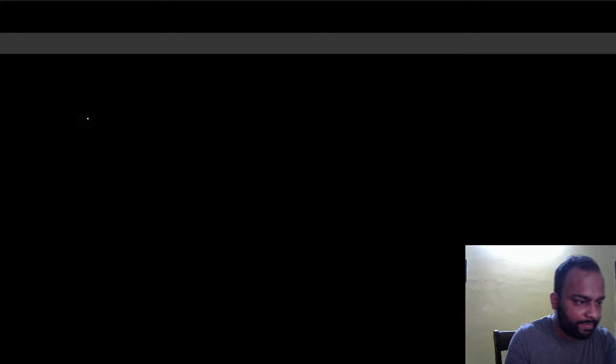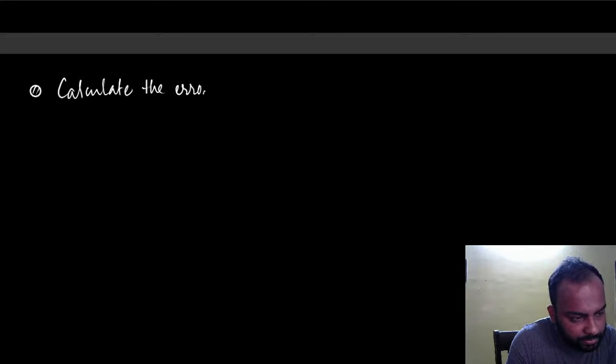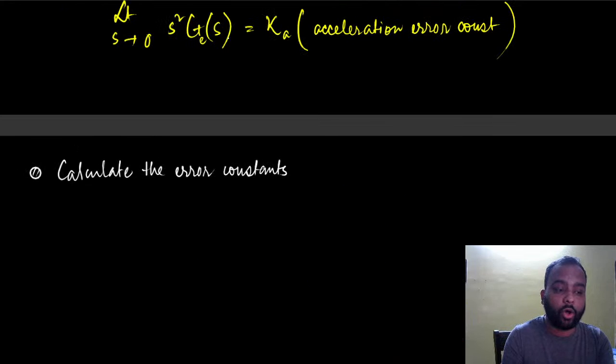So if I give you a unity feedback system, no issues, carry on. If I give you a non-unity feedback system, then you have to calculate it accordingly. All right, so let's solve a problem with non-unity feedback. So the question would be something like: calculate the error constants. Just one more thing, these error constants are also known as static error constants, because they are error constants for steady states.